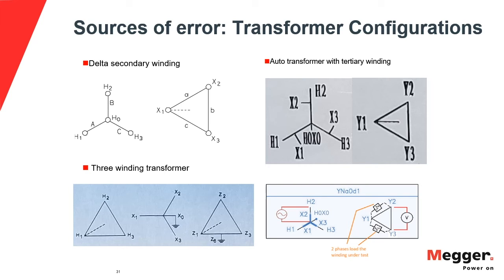When we discussed the concepts for TTR testing, we said that for the voltage ratio we measure to equal the TTR of the transformer, we need one condition: the winding we are inducing the voltage to should be open circuit, or have no load on it.